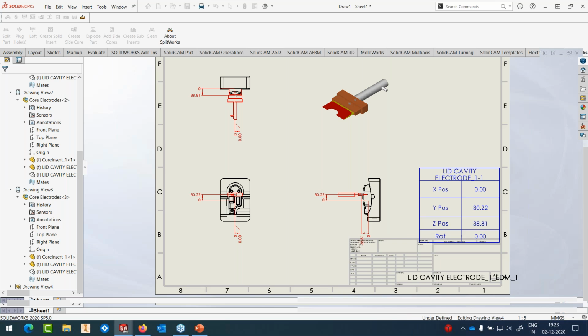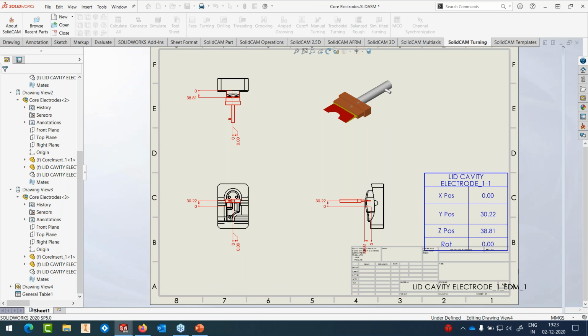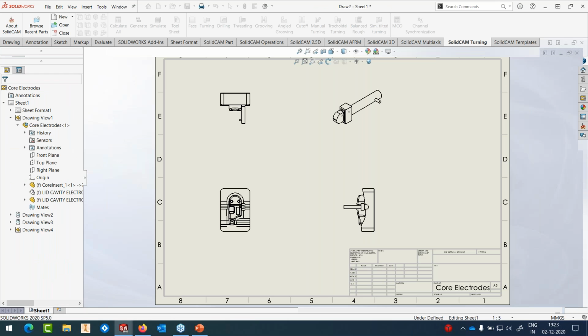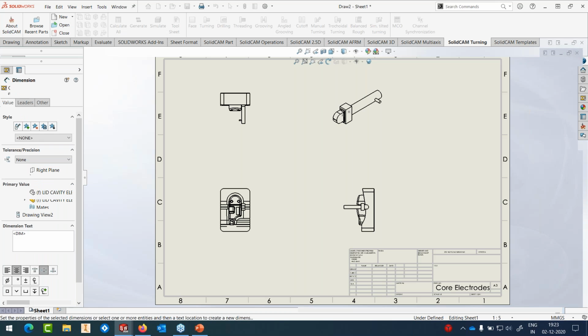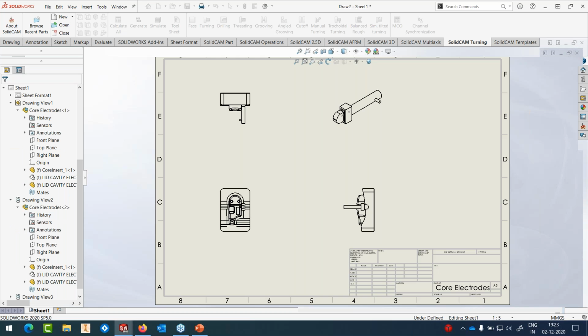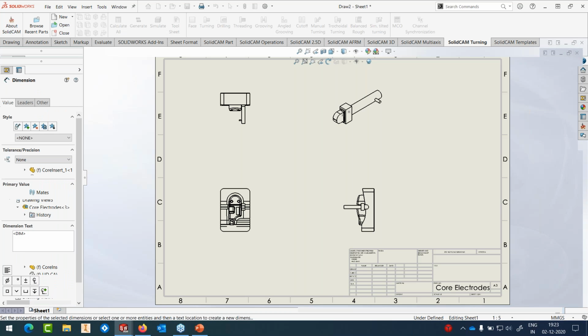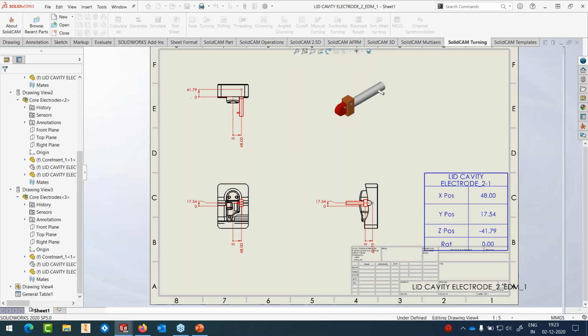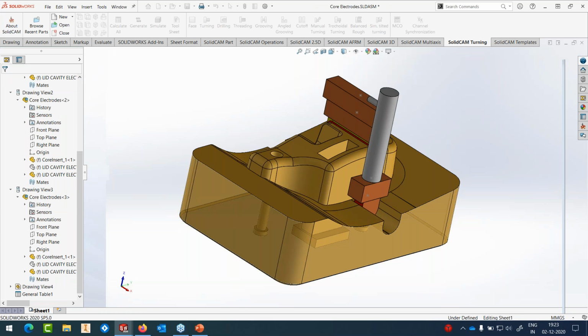Goran, you asked me about how you can define the clearance between the electrode and the model. I just showed you on one of the electrodes, I applied a spark gap. So that created the clearance. In event the electrode is really very complex, the spark gap may not work. In that case, the spark gap needs to be given as a negative offset when you're doing CAM.